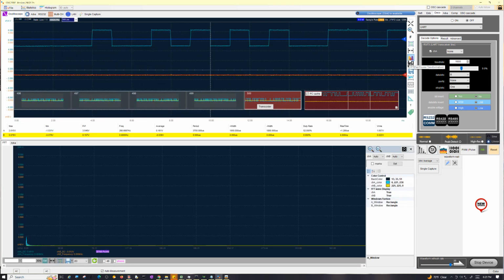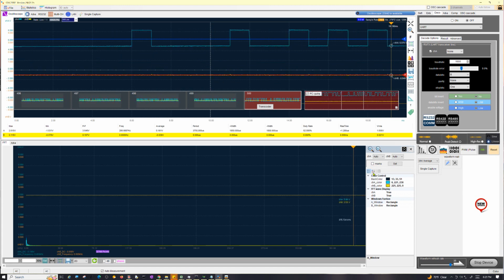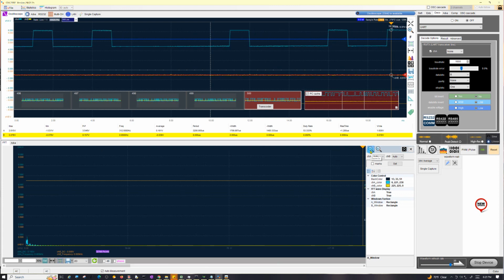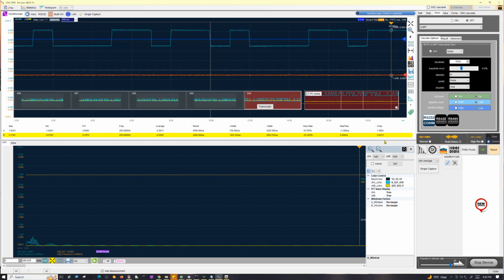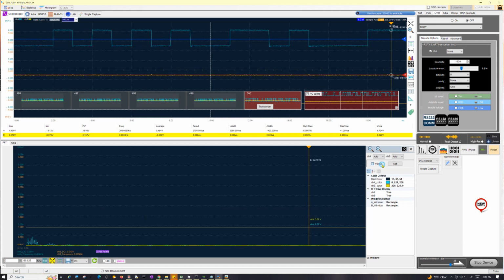this right here is a spectrum analyzer. This adds marks to it. This allows you to zoom in to it. But there are kind of limits to some of these things. 380 kilohertz is what it's defaulting to here. But you can enter your own frequency range here.